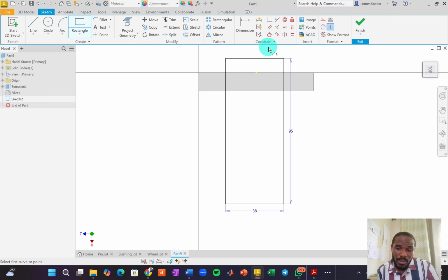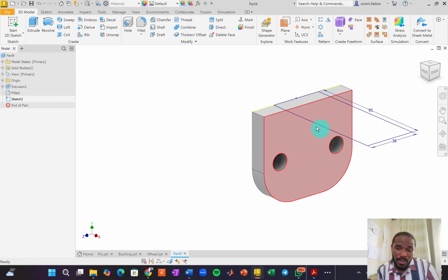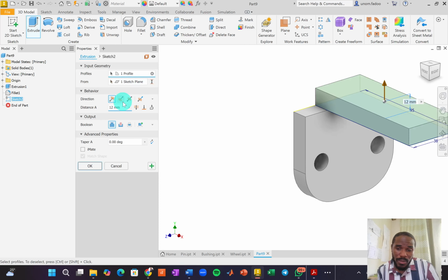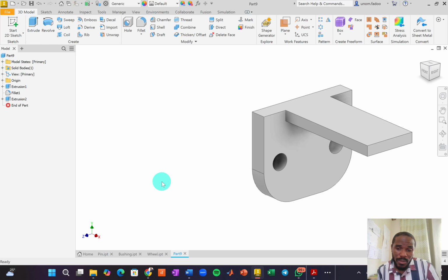So I'm going to pick my coincident constraint to look for the midpoint of that line, and I want it to coincide with, oh, I did not project, did I? Oh no, it's there. Yeah, bang on, that's what I want. Right click and OK. It's fully constrained. I'm happy. I finish sketch. Great. So now I'm going to pick my extrude tool, select that. Automatically it goes up, but I want it to go down, so I'm going to flip it down, but it's also selecting cut. I don't want cut, I want it to join, give me a new material, but go down by 7.5, right? Now that's what I want. I'm happy. I click on OK.